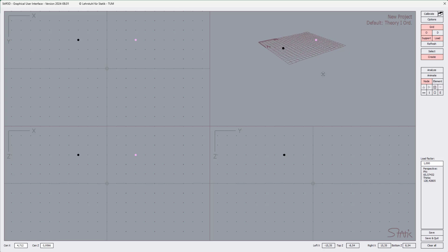Okay, let's now generate the third node here on the top level, which would be at x equal to -3, and y equal to 3. So again going down to the bottom left. So x should be -3, top, we come to z, should also be -3, again top. Yeah, x is okay, then we come by another top. Pressing the tab key to the y coordinate, which we now choose to be 3, and we press the return key, and voila, again updating the grid. Now we have the third node here at the top level.